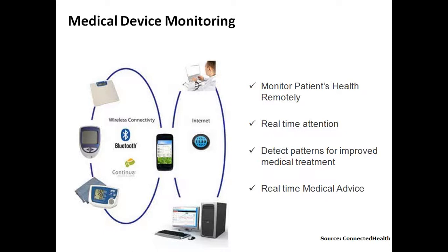I see solar panel monitoring, but I see some of the pictures missing in the slide. But essentially the missing slide is the backend monitoring system as you saw in the DG monitoring. Solar panel monitoring is yet another very interesting application because of machine-to-machine. And what it does is, in your solar panel, you typically have a charge controller or an inverter or an MPPT controller that is installed in the solar site. And you can connect a monitoring device, which is again operating on a cellular network, that transfers the data over the internet to a remote monitoring site.